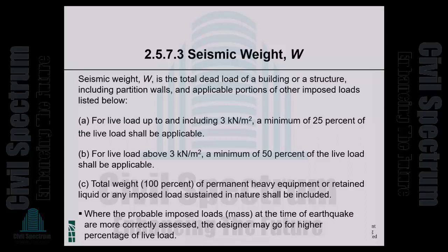Okay, so seismic weight is the total dead load of a building or a structure, including partition walls and applicable portions of other imposed loads listed below. Live load up to 3 kilonewton per square meter, a minimum of 25%. For live load exceeding that, minimum of 50% of the live load.